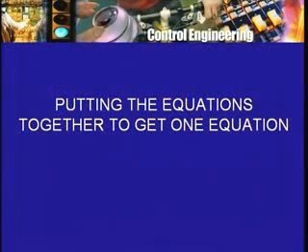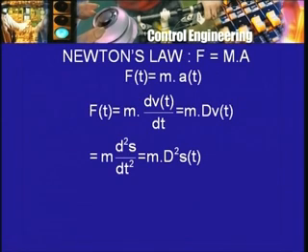Now of course we have to think of putting these four electrical devices together, or the mechanical components together, to get the electrical circuit or network, or the mass spring dashpot with a force or a displacement source on the other hand, and continue with these equations, but write down some more equations whereby one will see that the analogy will extend further, and finally we may be able to write down one equation for the electrical network and one equation for the mechanical system.